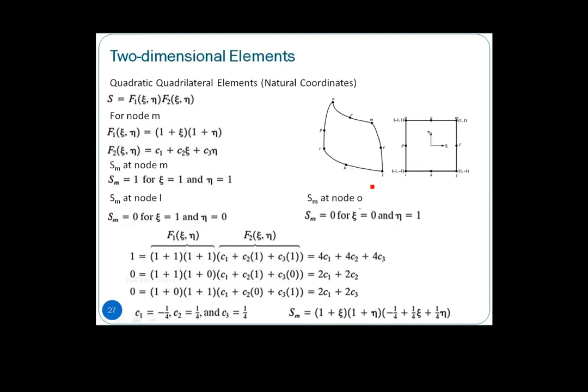So how can we derive the shape functions here? We separate into two parts. One is the corner nodes. The second part is the midside or midpoint nodes. So we start with I, J, M, N, followed by the mid nodes, which are K, L, O, P. For these I, J, M, N, four nodes, we can actually treat the shape functions